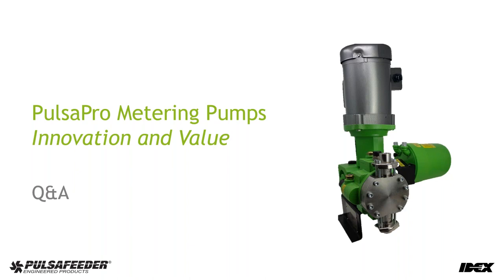I saw that, and it sounds like we got two different things being referred to in there. So the window for the hydraulic bypass valve, you should not normally see any oil in there at all. You would only want to see oil in there when it's bypassing, which means you have a system upset situation. On the other hand, on the top of the pump, you have the push to purge valve and its diagnostic window.